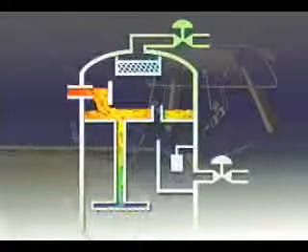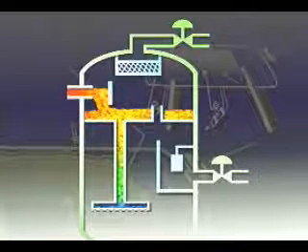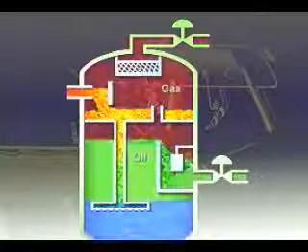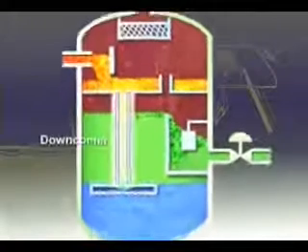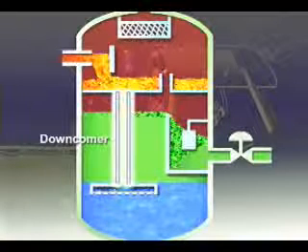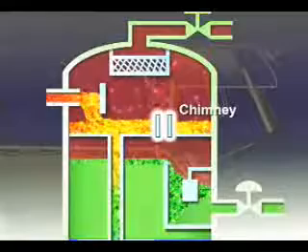In a vertical three-phase separator, flow enters the vessel through the side. As in the horizontal separator, the inlet diverter separates the bulk of the gas. A downcomer is used to transmit the liquid through the oil-gas interface to keep from disturbing the oil skimming action. A chimney equalizes gas pressure between the lower section and the gas section.